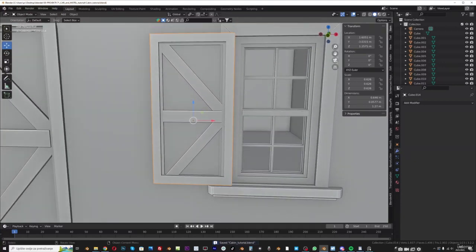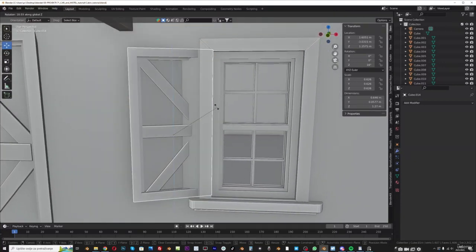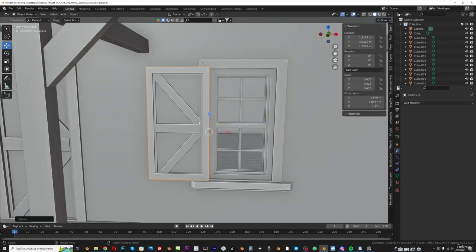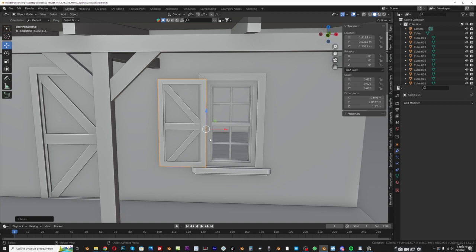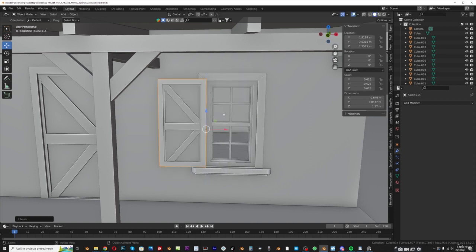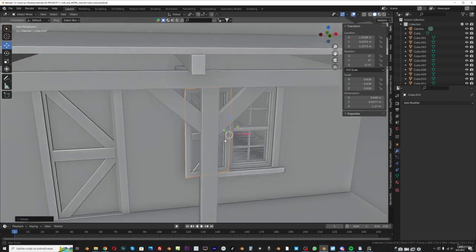And I want to rotate this window a little, so if we go with rotate Z, we rotate this from the middle of this origin. But if we go to options and click here, Origins, transform from origin, we can move this origin here. And let's turn off this option now. And now if we press rotate Z, we rotate this from this origin here. And I will rotate this just a little.